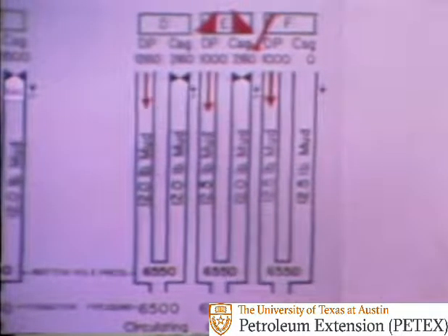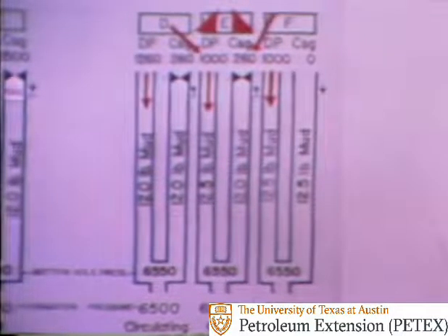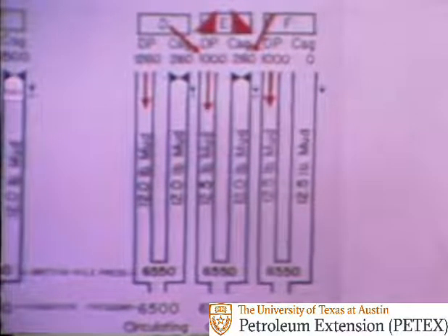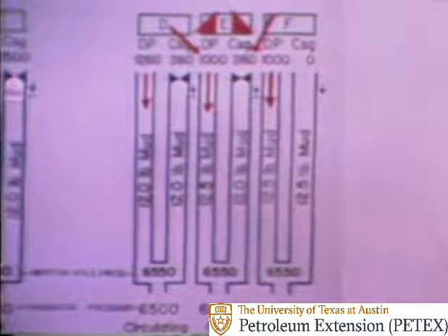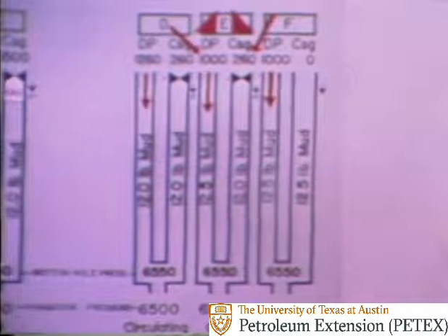As soon as the drill pipe has become filled with the heavier mud, it will be found that the drill pipe pressure has been reduced to the pre-selected circulating pressure, or about 1,000 psi. Control is then shifted back to the drill pipe, wherein the drill pipe pressure is held constant at the reduced pressure by continued choke adjustment.